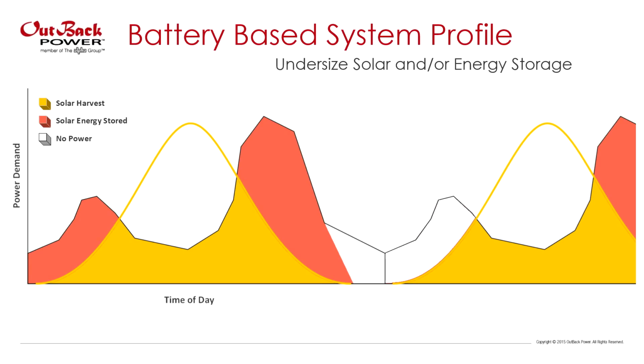If you were to undersize your batteries as well, not only the PV array but also your battery bank, you could also run out of power and have an outage until the morning or afternoon. So it's really important to size your array and then your energy storage, and make sure that you're sizing them appropriately between the two.